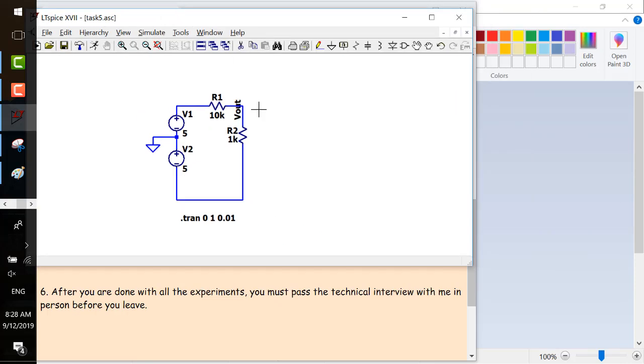Whenever I'm testing, this is a really good example actually. When we directly use the entire voltage drop times the share, we usually can get VL, right? But this time we cannot. The reason is the other terminal of this resistor is not 0. It's -5, right? Did you get that? Which means the voltage drop across R2 doesn't equal VL.